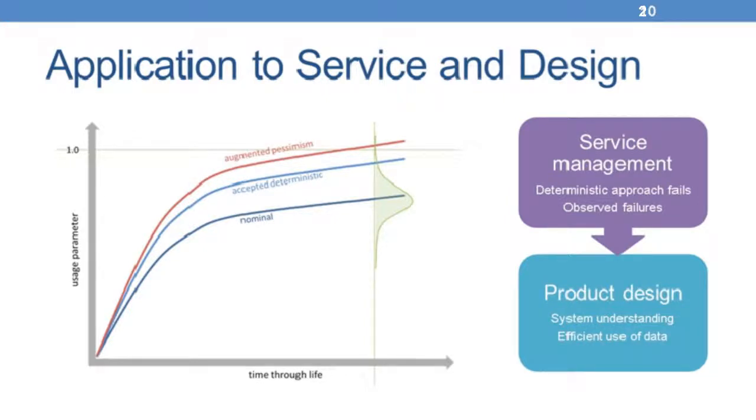Because we don't live in a perfect world, there are often things like manufacturing non-conformances or plant operating excursions that we have to account for, which, if you assess using the original regulator-accepted deterministic approach, will apparently fail as you're already close to the limit. And this is what the red line on the graph is representing. Now, if you take a nominal view of the inputs, there will be a large margin present. So the question for us is how to demonstrate and quantify an acceptable level of conservatism.